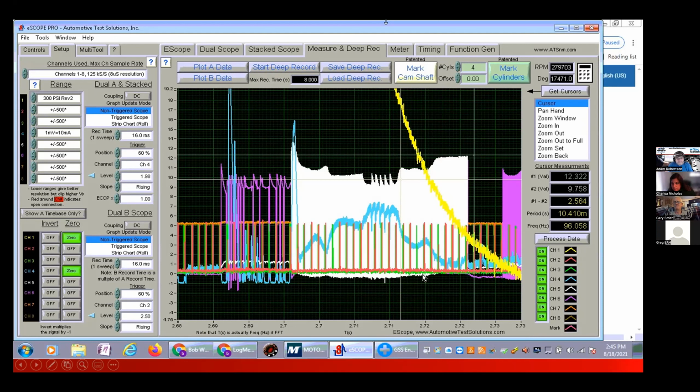See that? I might just add one thing to this. Being I just dealt with the one you were talking about earlier, Gary, I expected, with my amp clamp around just one of the phase wires to the fuel pump, and this is a 3-phase pump controlled by a fuel pump controller, to see somewhat of a sine wave. Not at all. It had a funky step as it comes up, and then another step as it comes down, apparently because of the chip design and the way it turns on and off.